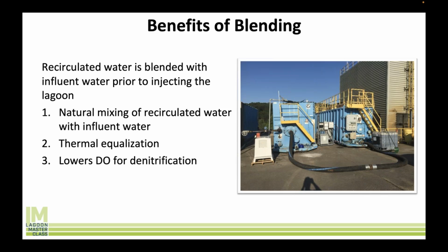I learned this because obviously we've got influent BOD coming in from the collection system. So that's good. We want to get the nitrates in contact with that influent BOD, which is naturally growing the heterotrophic bugs, right, that then want to denitrify.